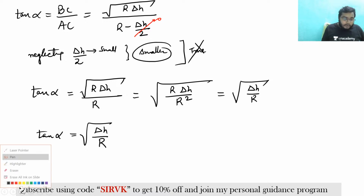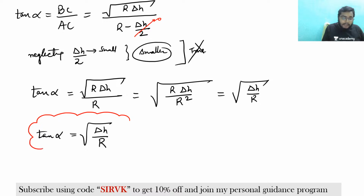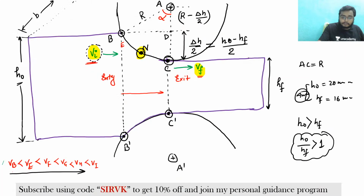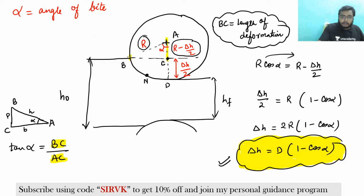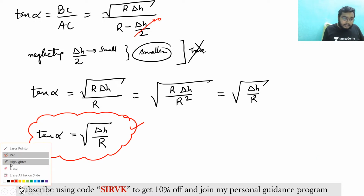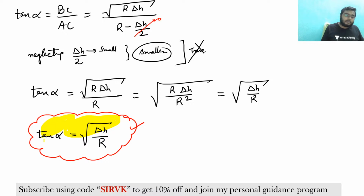So you can remember this formula also, or I would say that I have given you this formula, right? What formula? Delta H is equal to D into 1 minus cos alpha. Sometimes it is very difficult to remember this formula, because again delta H is there, the radius of roll is there, and alpha, the angle of bite, is there. So you can always remember this formula. If you cannot remember that formula, you can remember any one of these formulas, okay? Because this is again the relationship between the angle of bite, delta H and R.